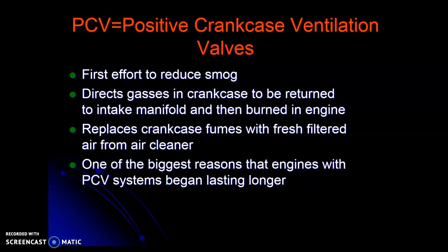So PCV, positive crankcase ventilation. Basically, here's what the PCV does. Remember way back when we talked about the engine in the four-stroke process, we have intake, compression, power, exhaust. We have that combustion chamber, we have a piston, you have rings. A couple of those rings are your compression rings, and you have an oil scraper ring. Well, those compression rings aren't perfect. When the cylinder ignites, some of that pressure that's pushing down on that piston makes its way into the crankcase. Along with that pressure is going to drag some fuel.